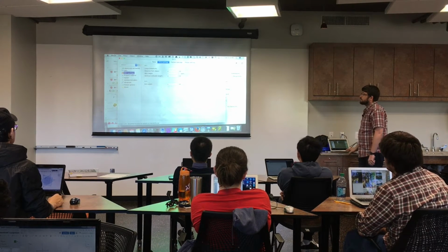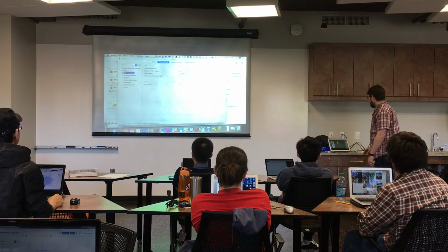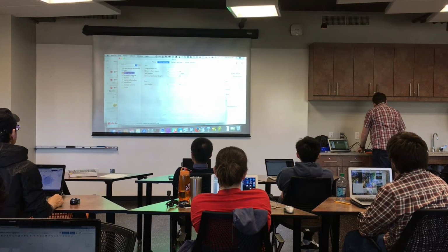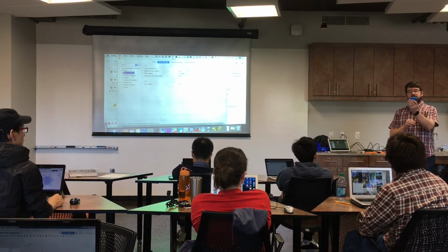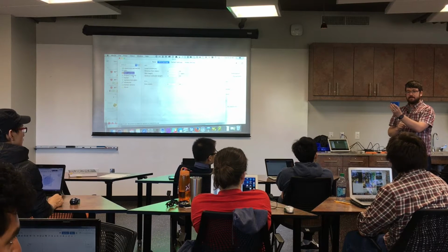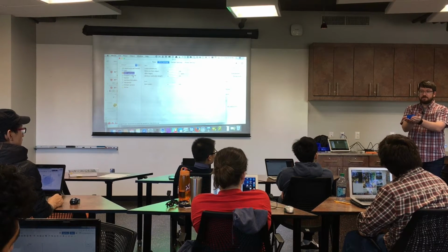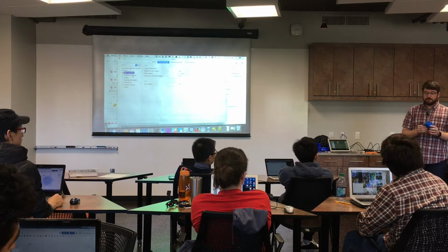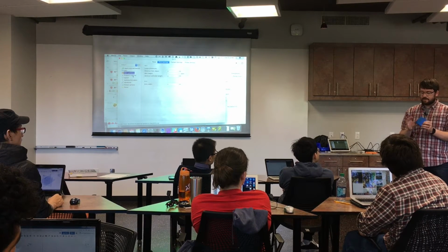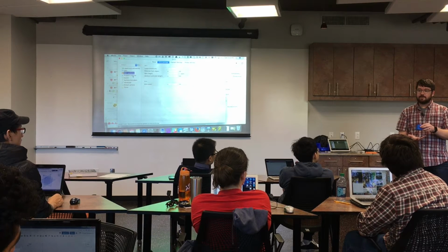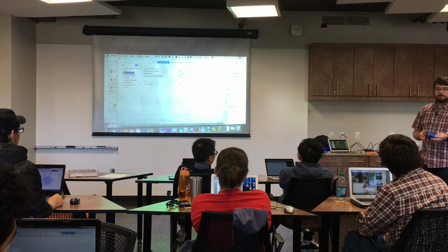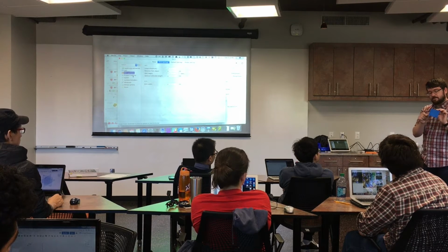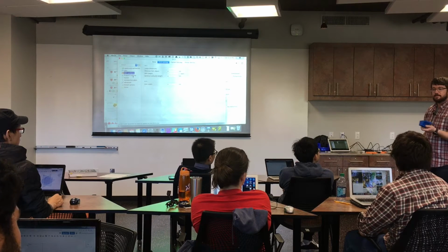You can add what's called a skirt and a brim onto the part, and you can add a raft. So sometimes when you're printing these parts, I don't have an example that still has the raft on it, but you can see this one's actually a little bit warped on the bottom. As I was printing it, it started cooling and the edges peeled up, which is not good. So you can actually print a thin layer that is much bigger than this, that adheres to the print bed better, called a raft, and then print this on top of the raft. And then you just rip the raft off and throw it away later. So they might do that for you if they think your part needs it. A brim would be just adding some material around the edge that you'll peel off and nothing under it.